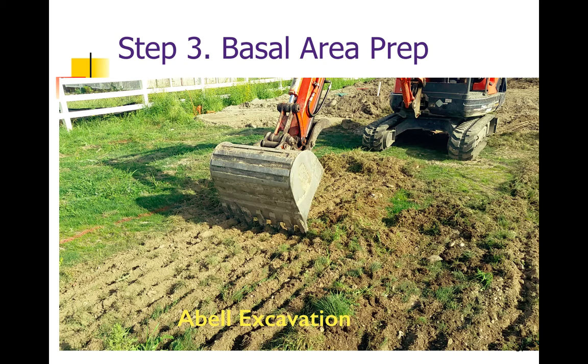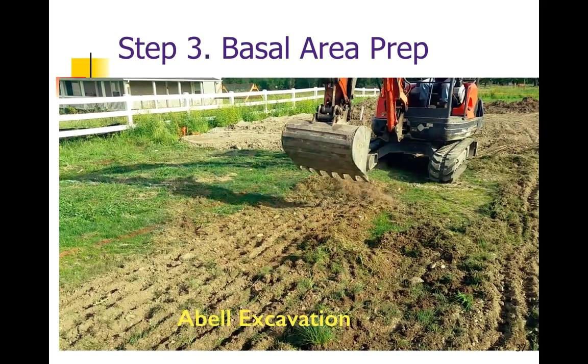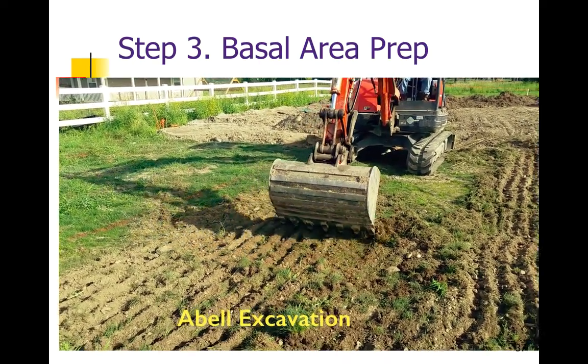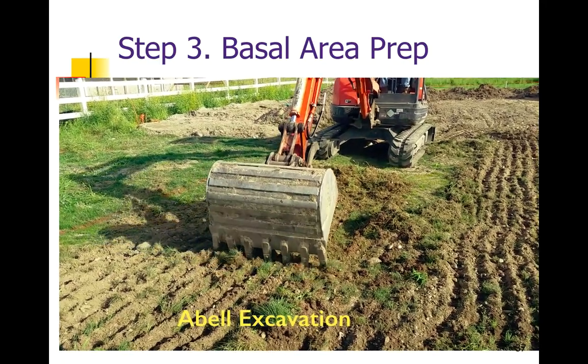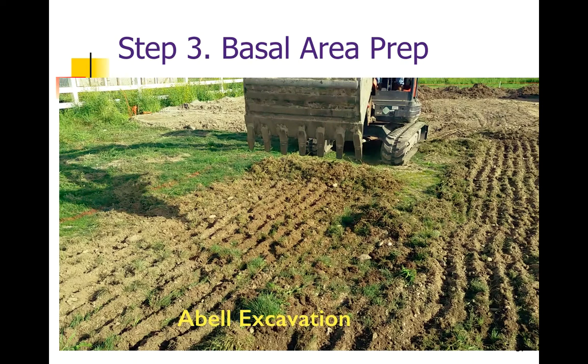The basal prep is quite simple. Regardless of what type of equipment that you operate, you'll just want to take the teeth and just insert them into the ground, maybe 2-3 inches max. Make one swipe along the contour. Whatever sod or material comes up when making this pass, whatever is left in the ground, leave. Obviously, the material that's built up at the end of our scarification, we're going to remove that and cast that off to the side.